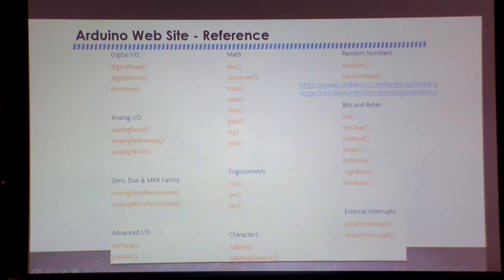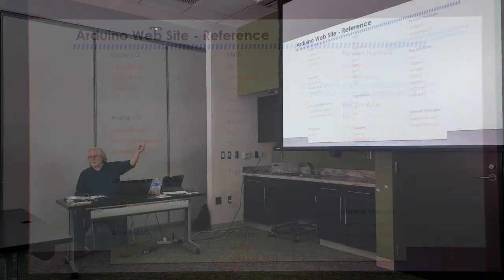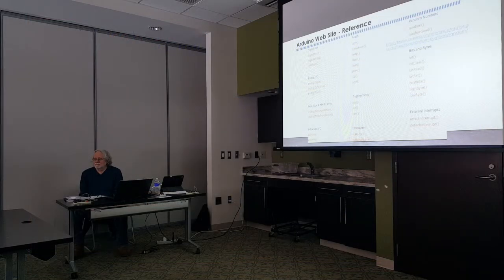And so what the command in the processor might be is port D equals something, and port D is 8 bits wide. These inputs and outputs are only 1 bit wide, so they've made it easy for you. For the person who's learning how to write C and how to use the Arduino, these functions simplify everything, and simplify the commands that they're trying to create.